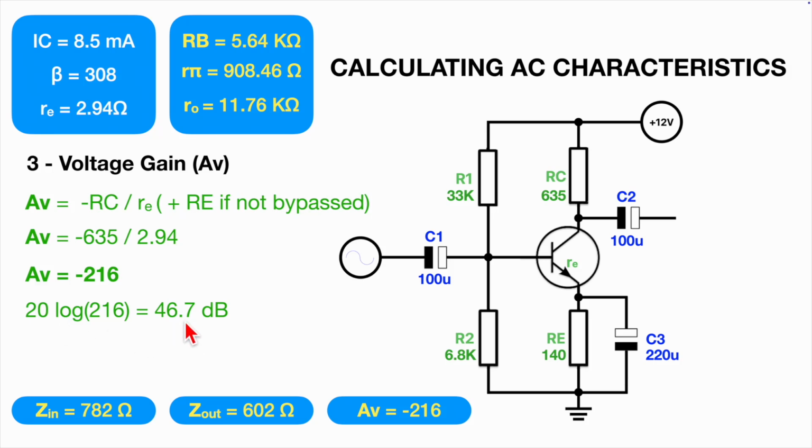So, a lot. What you can do, of course, particularly if you want to stabilize this circuit, is that sometimes people want a little bit of resistance here from an AC point of view. So you could split this resistor. You could say, well, let's have a 100 ohm resistor in series with a 39 ohm resistor, say, and we'll bypass for AC the 100 bit, but we'll keep the 39 ohms in, so the AC signal will see that.